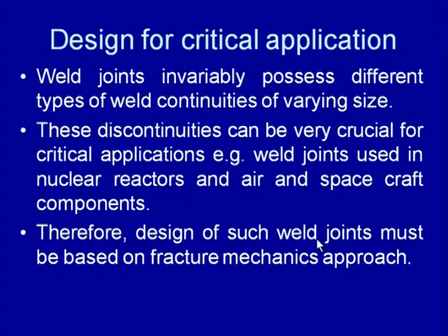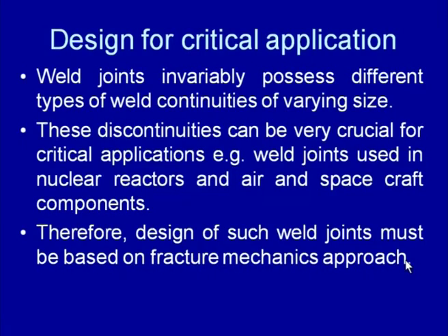Therefore, design of such joints must be based on the fracture mechanics approach. A conventional design approach does not consider the presence of these discontinuities, but when we consider the fracture mechanics approach for designing a weld joint, we take care of the presence of the discontinuities in the weld joint, material properties and the external applied stresses.